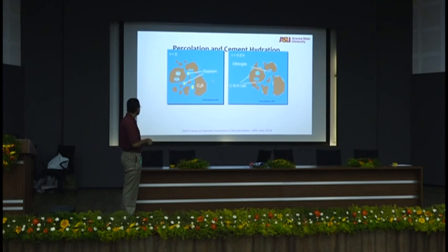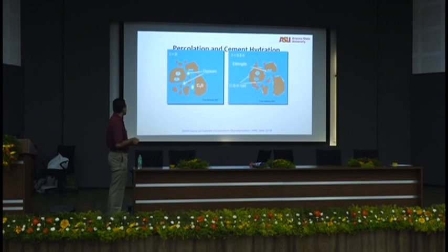And then what is all this blue? Whenever you see blue, it's the ocean, right? It's all water. Now, after some time, half an hour, you have ettringite that is formed, right? Ettringite consumes what to form? Gypsum and C3A, right? So you have ettringite that is formed. This C3A is gone, so that's why it's showing it as a void, because that gets consumed to form the ettringite.